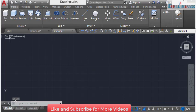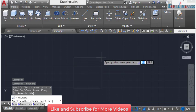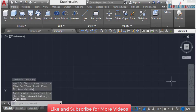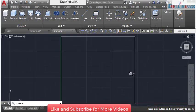So now the view is going to be top, and next is to select a rectangle and click on rectangle. Now at any point I will start my drawing. So I'm going to enter a dimension of 4500, 4000, and then press enter. Now select the zoom extents tool so you can see this. Right click and select zoom, and then zoom in.